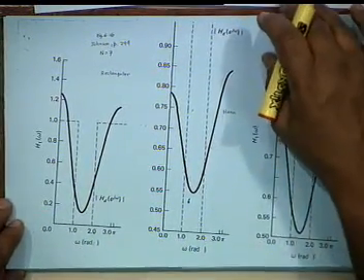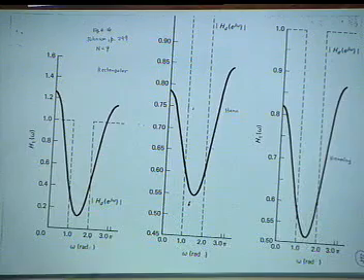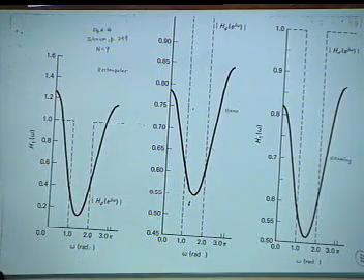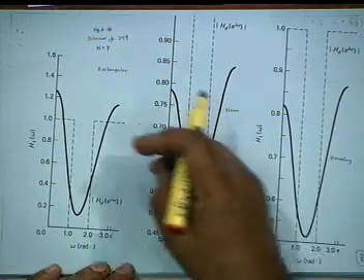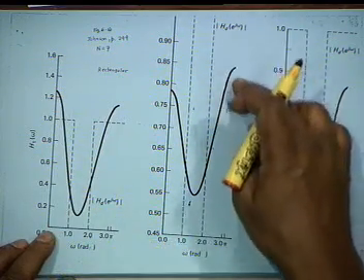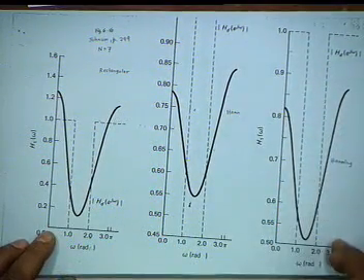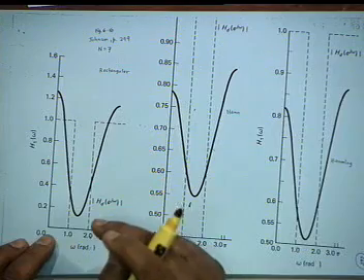Once again, if you want to compare, you have to plot them on the same figure, normalize the maximum magnitude to 1. You see, the maximum magnitude here occurs at omega equal to 0. Here it occurs at omega equal to pi, here also at omega equal to pi. So, in the normalization also you shall have to be careful.